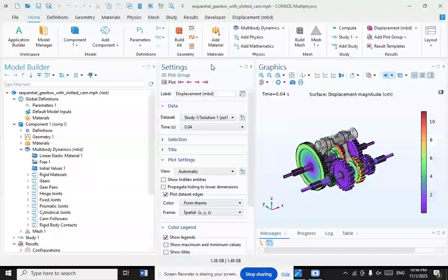The assembly consisting of both the input and output shafts is referred to as the main shaft. Also, sometimes this term refers to just the input shaft or output shaft. Independent rotation of the input and output shafts is made possible by one shaft being located inside the hollow bore of the other shaft, with a bearing located between the two shafts.